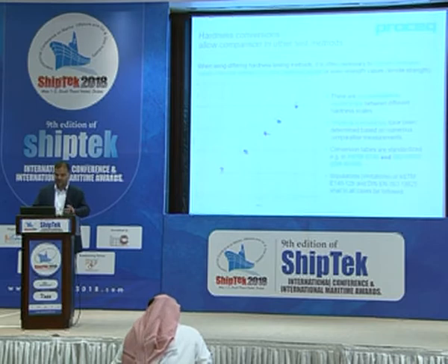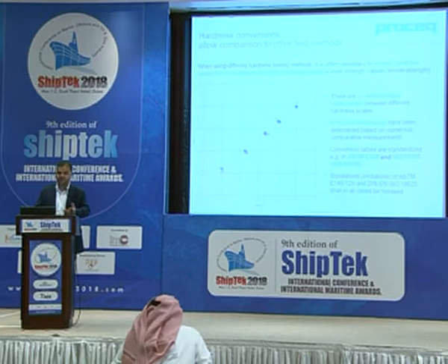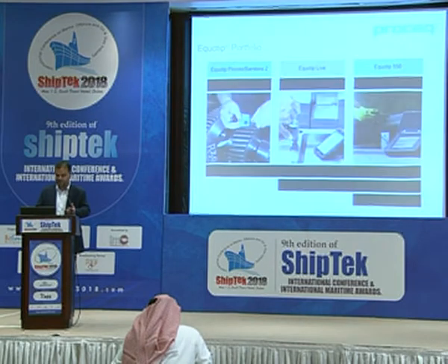Hardness conversions allow comparison to other test methods, no mathematical correlations. There's no empirical formula for mathematical correlation. It's the conversion as per the ASTM E140, ISO 16825, which are the standard tables accepted worldwide.